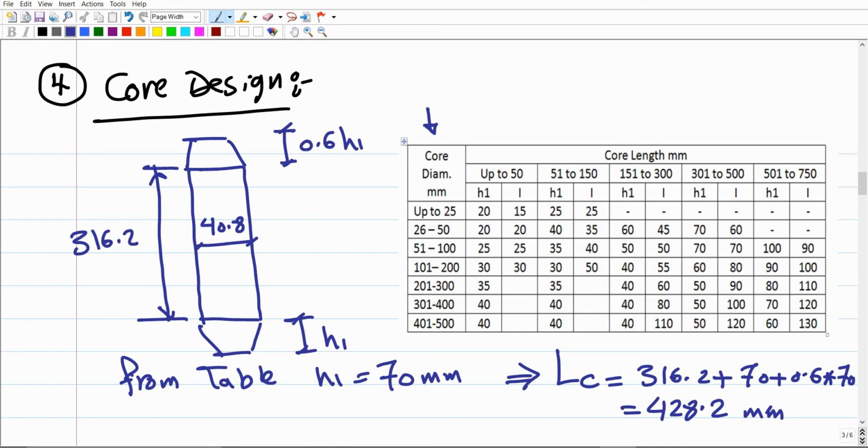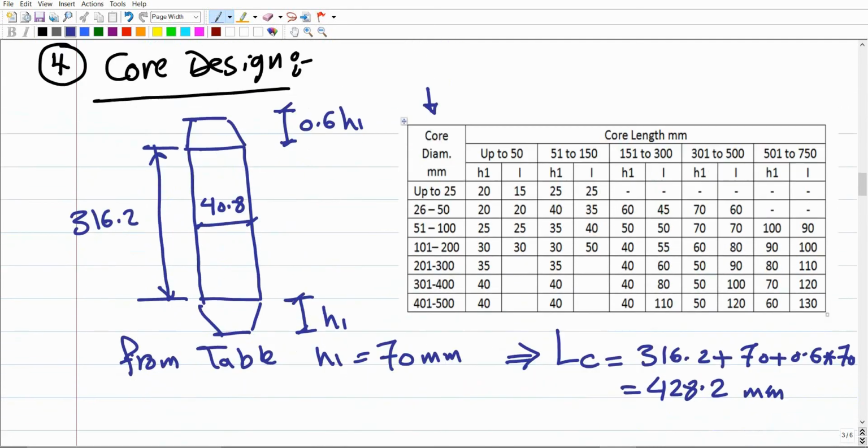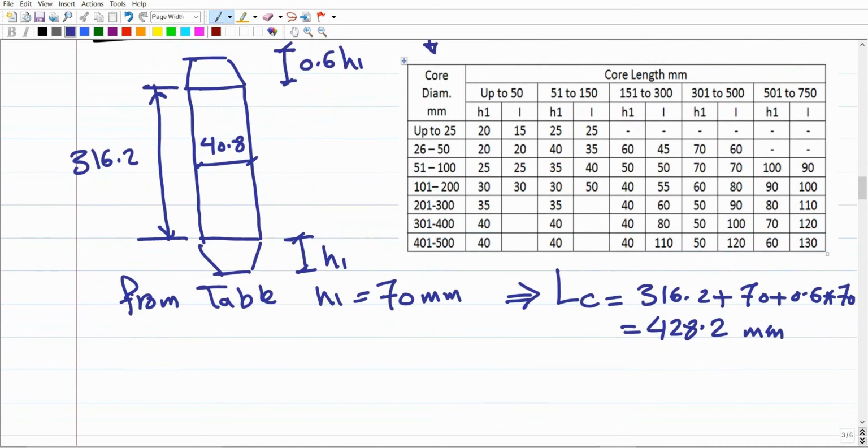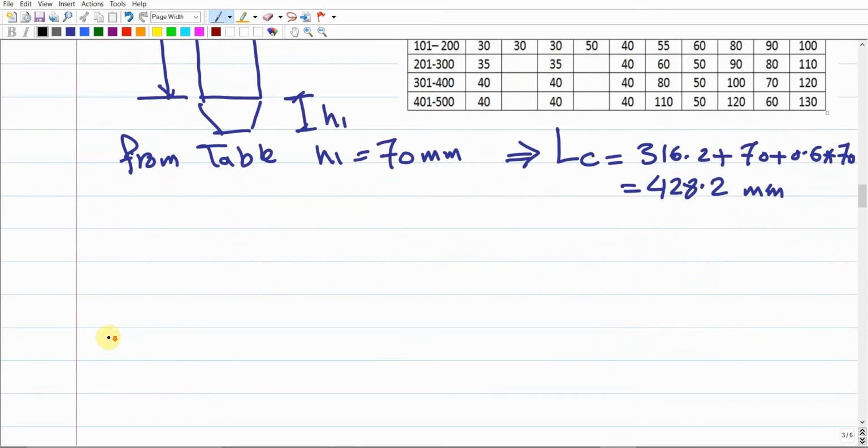It means that to come up with the volume or the gross weight of the molten metal, we're going to calculate the volume of the mold cavity. Then we are going to add the 30% to this volume to end up with the total volume. Then if we multiply times the density, we're going to come up with the weight in kilograms, the gross mass. And this is the objective of step 4. So moving forward to step 5.